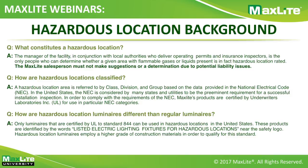In terms of how hazardous locations are classified, like I said, the NEC, which is the National Electrical Code, will determine what class, division, and group rating fixtures need to have in order to be installed in a specific area. Certain facilities may have a combination of class, division, and group fixtures, or they might be standardized to one rating. And keep in mind that hazardous location luminaires are integrally different and also different in terms of the certifications that they need in order to be classified for such a use.